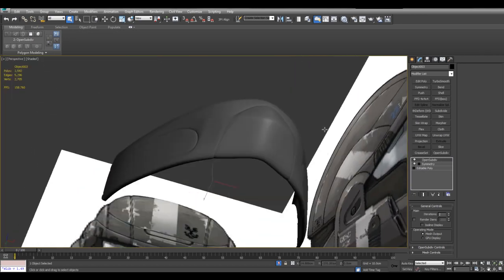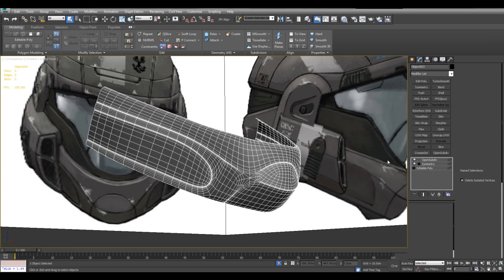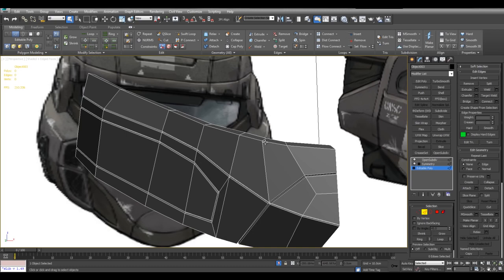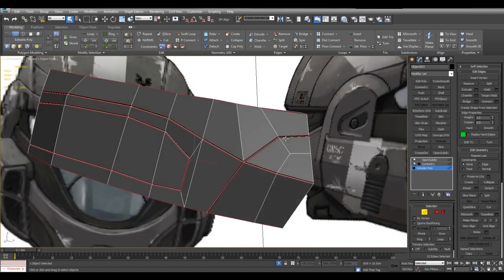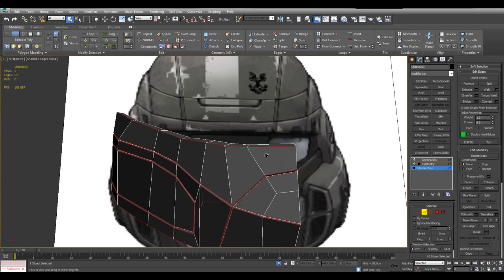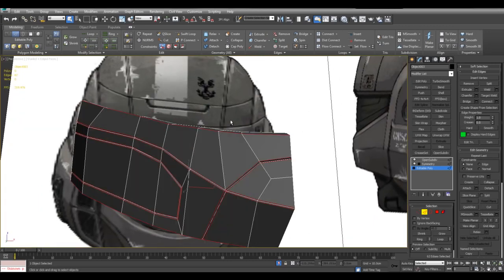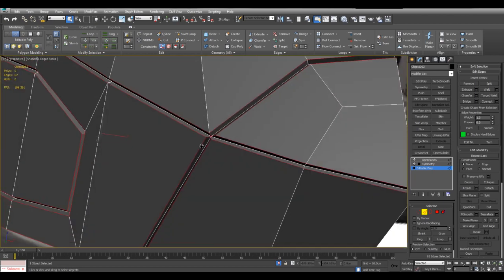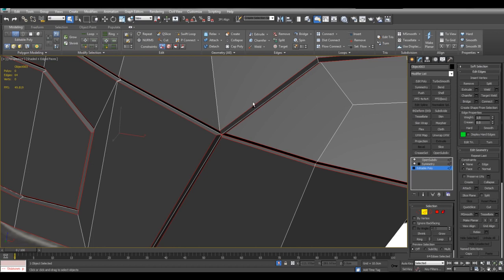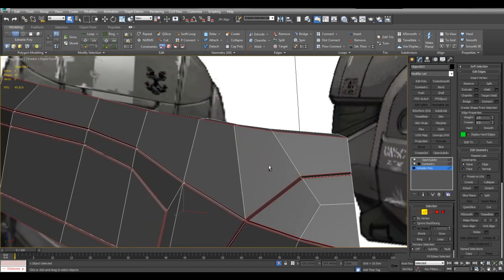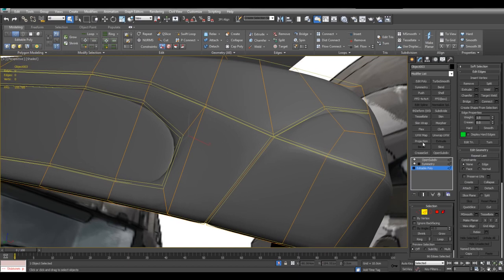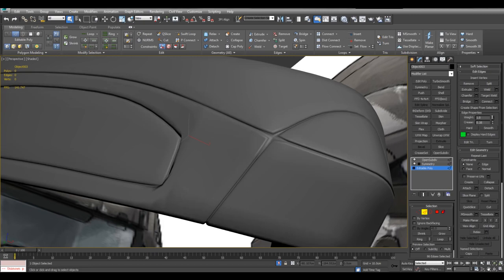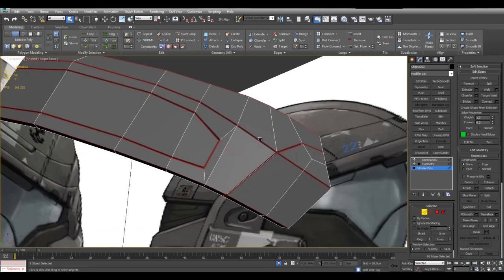And then I'll activate symmetry and open subdiv, and we can set some weights, some creases. So first thing I'll do is just clear all the creases. In this case I have none. Now I have a shortcut set to Control-Alt-C, which allows me to select all the convex edges. And I do have a previously made video about where you can find this and how you can set it to a shortcut. It selects all of the edges for me, but I also need to select some of the ones myself, like in the center here. And then I will turn off cage and increase the crease value here to make it sharp.